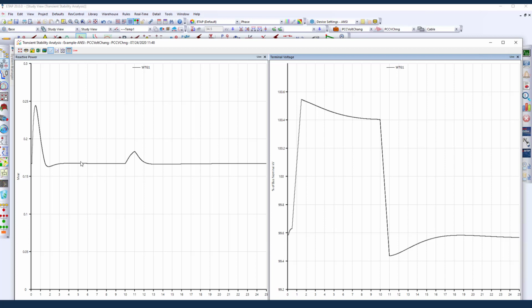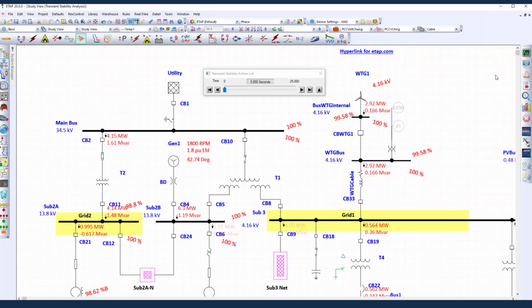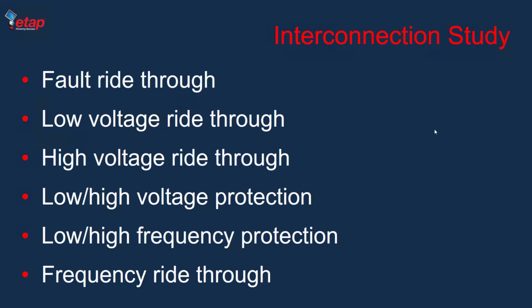And typically in a big power plant, each individual wind turbine is in Q control, and there's a power plant control itself that commands the Q to adjust the voltage at the point of interconnection. So you see that this is now a different performance depending on different settings on the WTG.